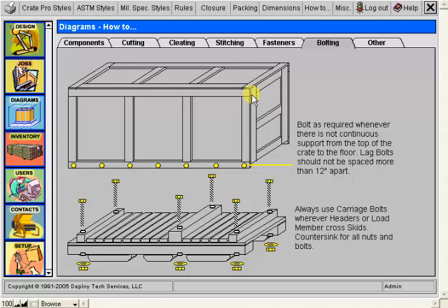Now that's probably not so important, but then when we get down here this gets more important because we have more valuable fasteners. The lag bolts are more expensive than the nails probably, and other fasteners can get a lot more expensive as well. If we're going to say here that we have fastener spacing of 12 inches, and this is part of the entire cap, well, our spacing value in the setup file is 4, and if we want these to be 12 inches apart, we need to put a factor in the inventory for these of 3, in which case 4 times a factor of 3 equals 12,